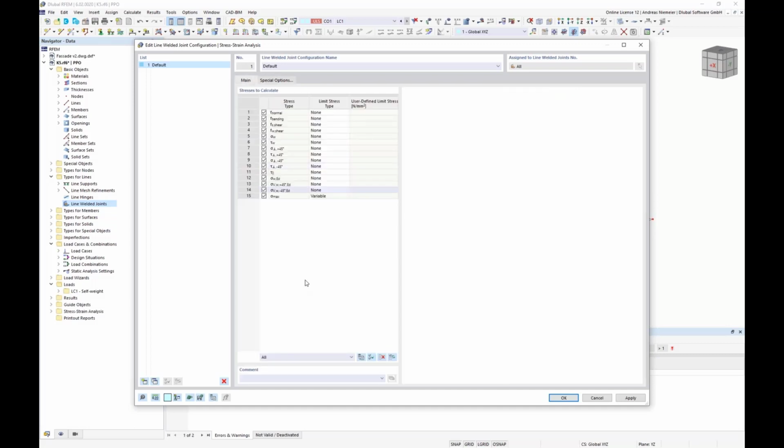And here, if you calculate the simplified system, you get a normal stress, a bending stress, a shear stress, and a shear along the weld line, and finally an interaction of everything where you can say, please check this value against the allowed limit weld stress, for example here 208. It's calculated according to the formulas from Eurocode, but you can use it for all other standards, therefore we made it open.